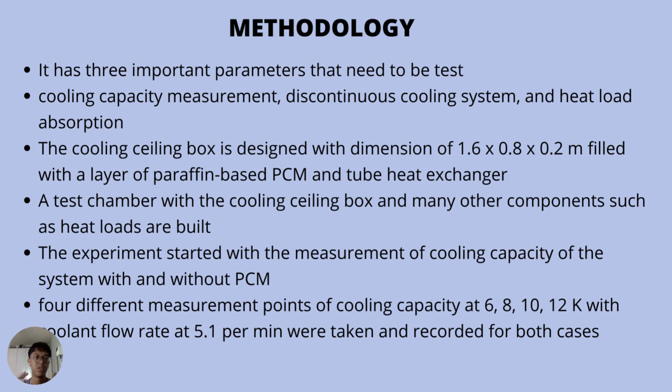Basically, the cooling ceiling box is designed with the dimension of 1.6 times 0.8 times 0.2 meter volume, filled with a layer of paraffin-based PCM, which is known as an organic phase change material, and also with a tube heat exchanger inside the cooling ceiling box. Also, a test chamber with the cooling ceiling box and many other components such as heat loads are built in the same space. The experiment started with the measurement of the cooling capacity of the system with and without the phase change materials.